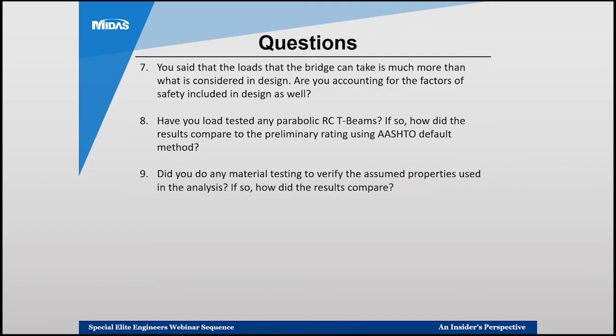Question number 8, have you load tested any parabolic RC T-beams? If so, how did the results rate using SDR? Yeah, we did. We had one big bridge that I had on the cover sheet, which is the US 11. This is a big project that we did. It's several miles long. It has 700 something spans of reinforced concrete curved or arched T-beams, and we did finite element analysis, both linear and nonlinear. And even with the nonlinear analysis, the capacity of the bridge for these curved or arched beams, or parabolic as you're saying here, is way more than that.